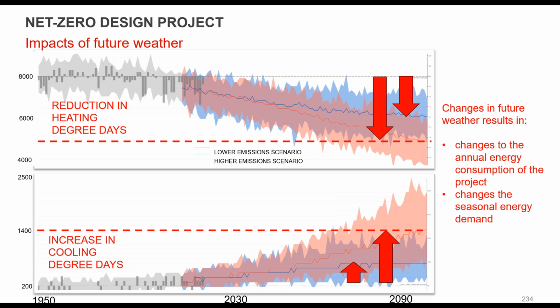I see a couple questions here I didn't catch. Kara asks, are each of these compounding? This was back on the chart that was showing natural ventilation and Passive House envelope and VRF. And yes, Kara, they are compounding. They're not individual in that case. They're a combination of starting with reducing loads, then efficiency of equipment and systems, and then finally PV, in that order.